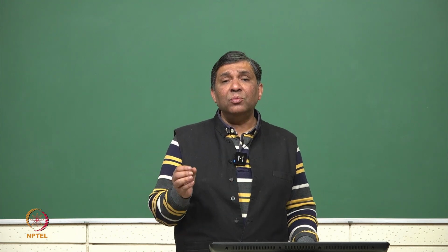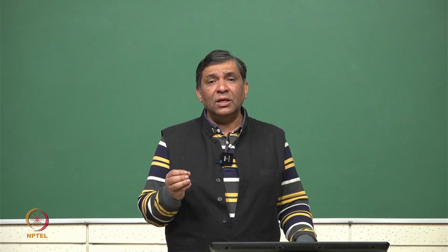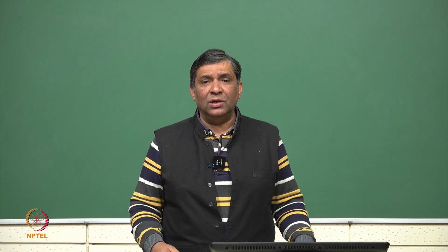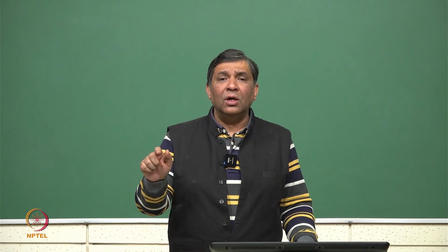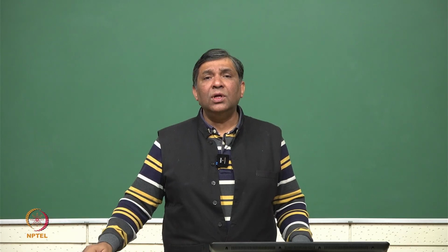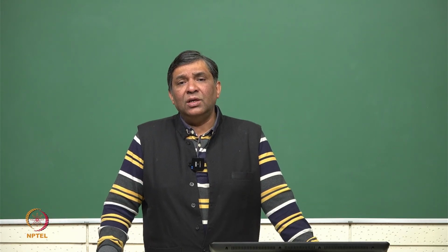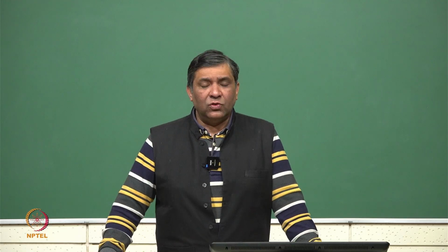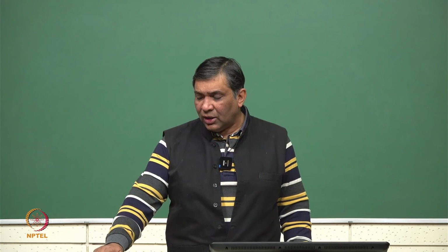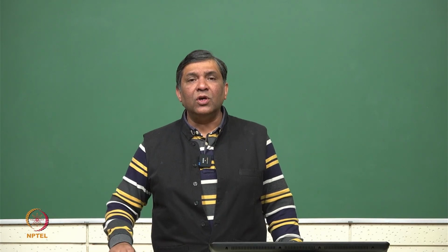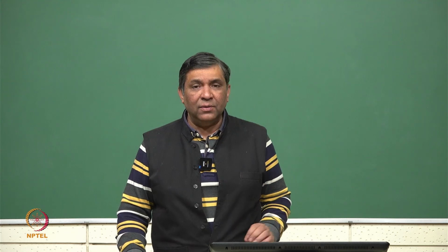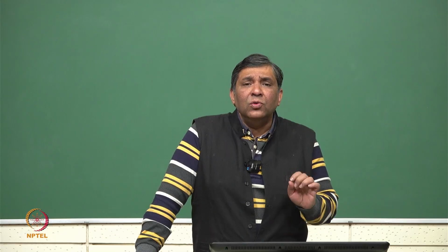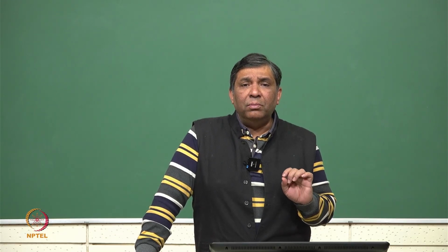And another important point which we discussed in our lecture is that it also has multiple exciton generation capability. That means, for a single photon it can generate more than one charge carrier, which can be used in the transport and the action of the solar cell. So, these are the major advantages of the quantum dot sensitized solar cell, using quantum dots to replace the dye.